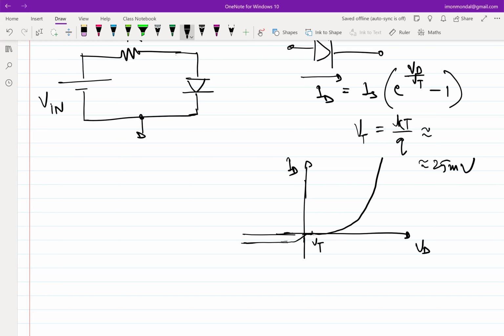Correct. Perfect. We can approximate that with change in current, voltage is constant. Right. Agreed. Then go ahead. That's why we can approximate that some current is flowing. Right. Exactly. So what his point is exactly right. It looks like for a small change in VD, there is a lot of change in current. So I can say that if the current has not changed much, then the voltage hasn't changed approximately at all, right? But now the question comes, why this 600, why this 650, why 700?